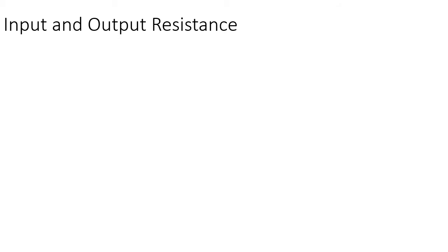Before talking about the output resistance of an op amp, let's talk about the output resistance of a voltage source. Why? Because remember that we said the voltage characteristics of an op amp is V out being equal to A times (Vp minus Vn), right? If you look at this, it is apparent that we can even define an op amp as a voltage controlled voltage source.